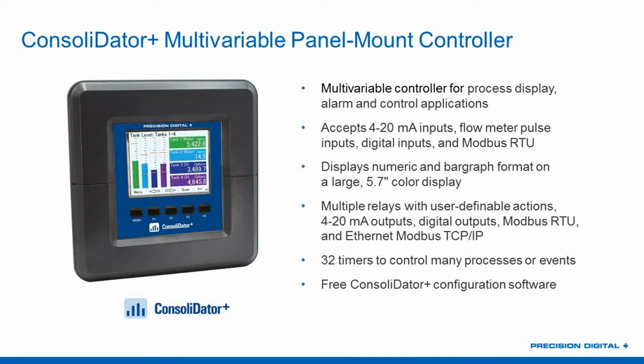You can get multiple relays in this. Potentially, if you didn't have any process inputs and all it was doing, for example, was reading Modbus values, I believe you could get yourself, pardon me for a moment here, I think you can do 30 relays, for example, on this. And those relays have user-definable actions. So we just say relays kind of as a generic term because they could be high alarms, low alarms, pump alternation, pump control. You can be using them for all sorts of things, sampling relays.